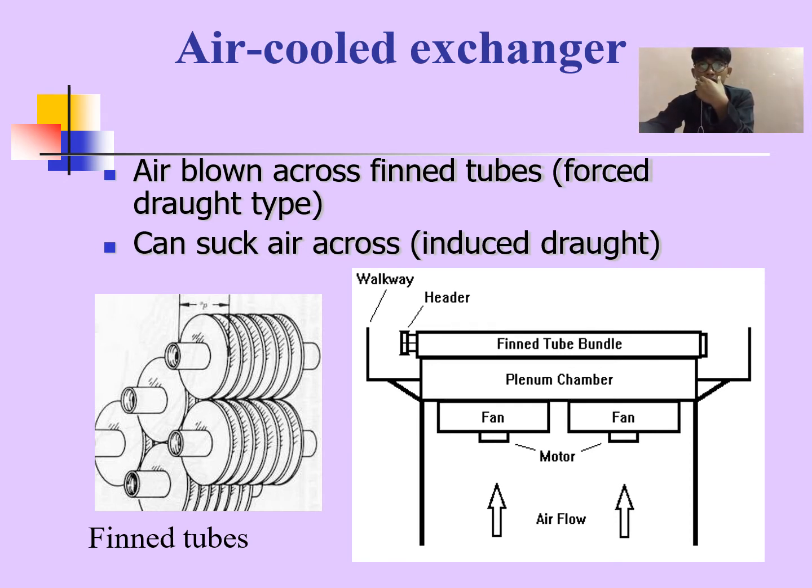The choice of whether an air cooled exchanger should be used is basically an economical question including first cost or capital cost, operating and maintenance expenses, space requirement, and environmental considerations.